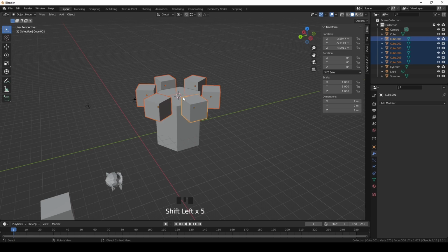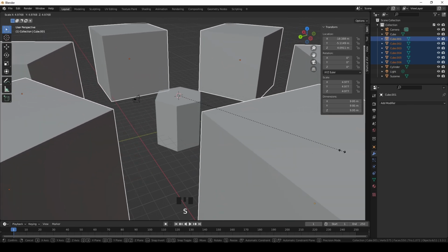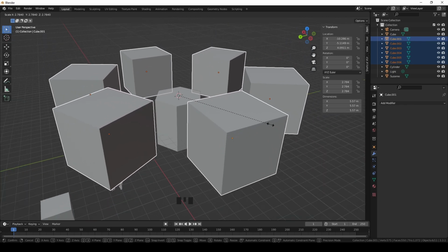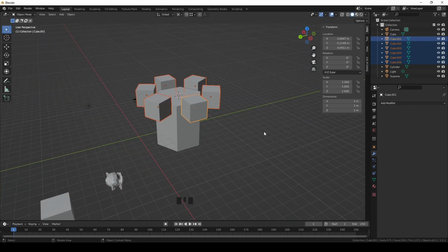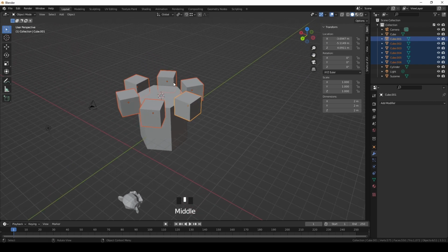In here let's scale our objects a little bit. As you can see, my object actually goes far away, but I don't like this. Press escape, go to the transform pivot point, and change your transform pivot point to individual origins. It helps every object use its own origin.